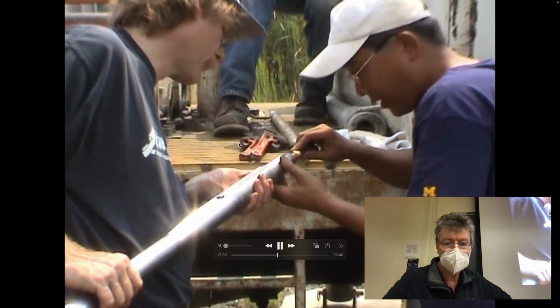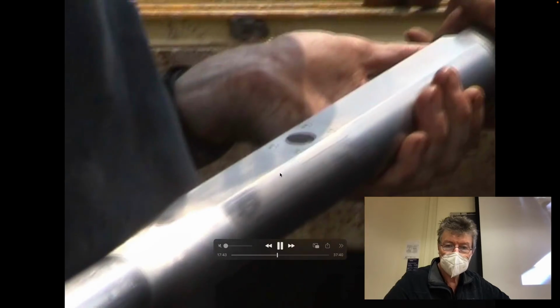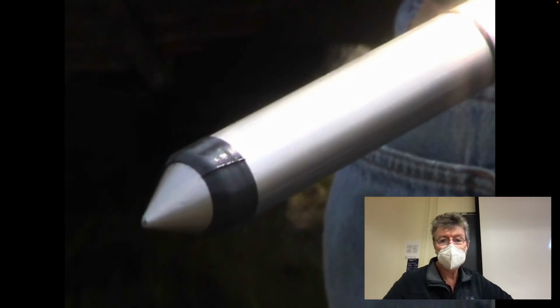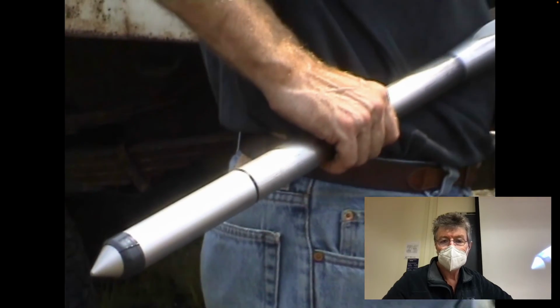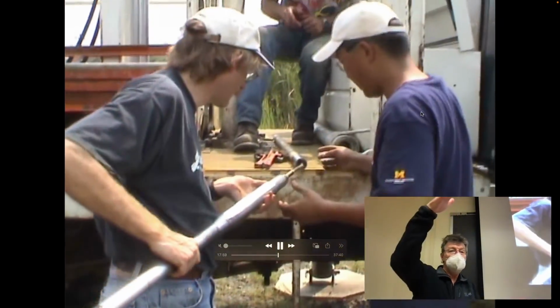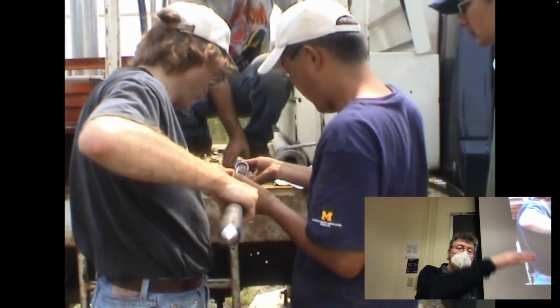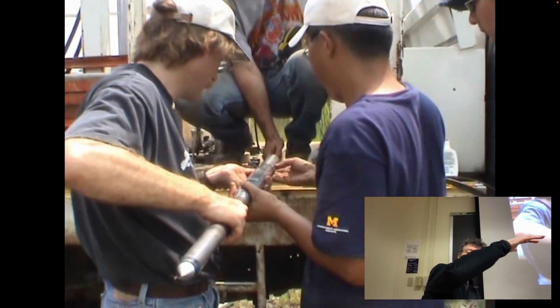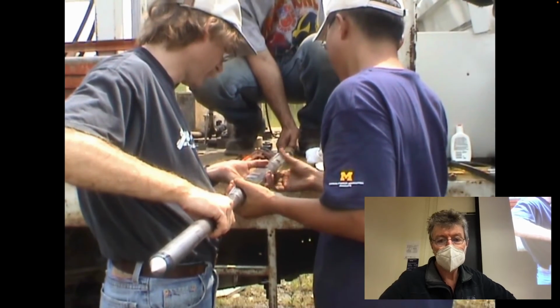Okay, this is the business end of the cone at the bottom. Here's a little window with a sapphire glass covering on it, and it just has a CCD inside there, like you have in your phone or in a camera, that takes video of what you're going past. It's behind the tip by exactly, I think, 1/2 meter, and so you see what the tip sees 1/2 meter divided by 2 centimeters a second later, and so you can coordinate the exact location.